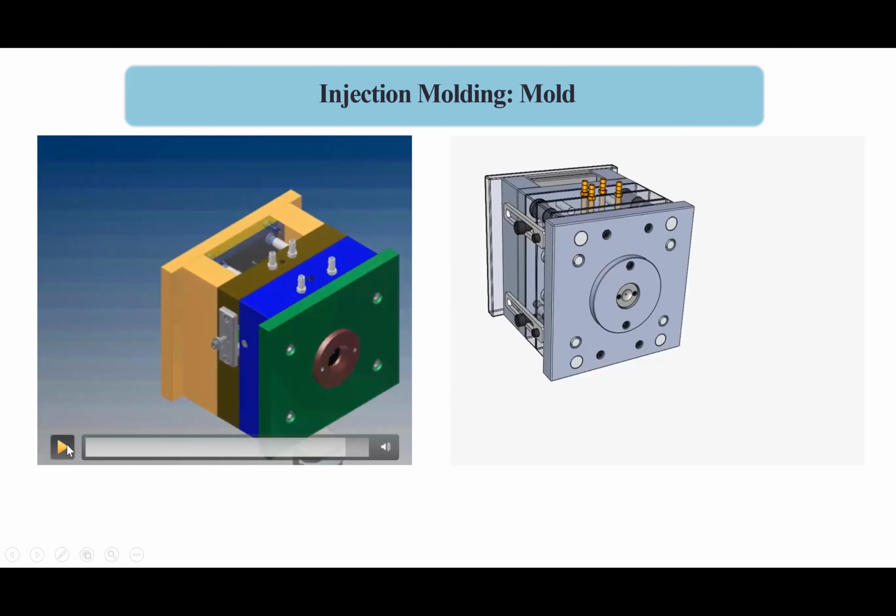In this video, this is the bushing that we are talking about. The nozzle sticks to this small hole, which is the bushing, and through the bushing the material is pushed into the cavity. Then the movable plate moves to the other side, with the help of ejector pins there.